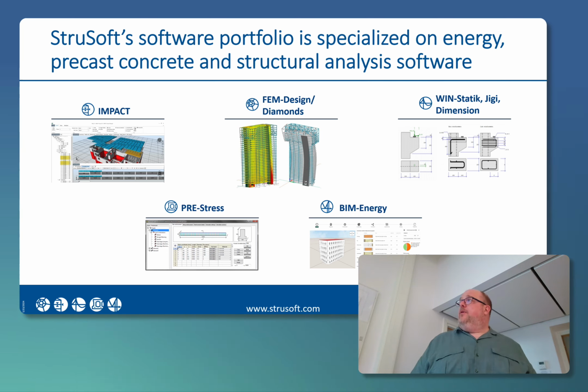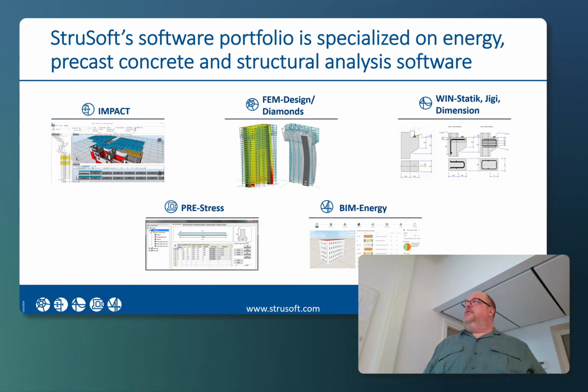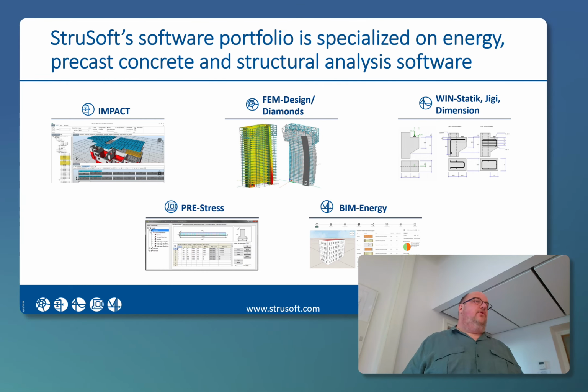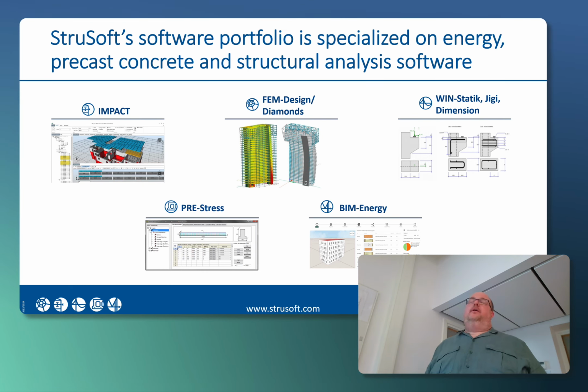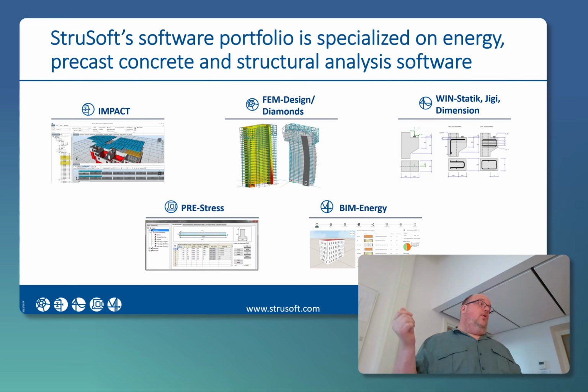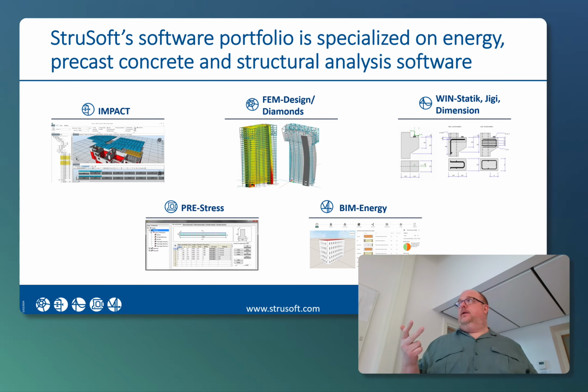And then we have FemDesign. Diamonds is an equivalent that is sold in Belgium. FemDesign is exactly just that. It's a tool for doing finite element structures, basically. Not really that much for elements. It's more about building the entire structure and seeing, if you apply the loads, like the snow and the wind load, what the forces acting on each individual element are, basically. You can do a design check according to code, like for steel, timber, and concrete.